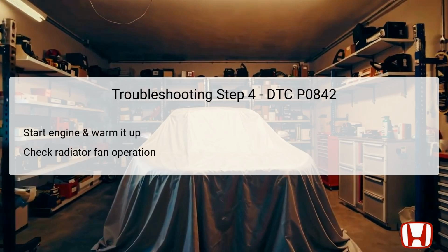Start the engine and allow it to warm up to the normal operating temperature, which you will know is achieved when the radiator fan activates. This step ensures that the vehicle is under typical operating conditions, crucial for accurate diagnostics.